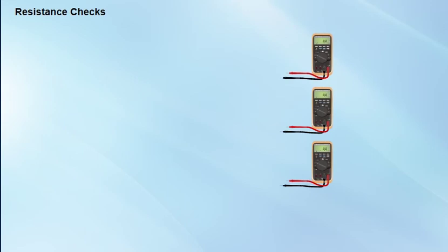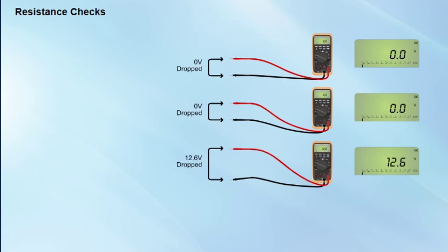A voltage drop check is used to determine if any connector, wire, or component in the circuit has excessive resistance, which means it is consuming too much electricity. To measure voltage drop, place the DMM test leads across a fuse, switch, load, or other test point. This test is used to determine excessive resistance by measuring voltage drop across the component while current is flowing.